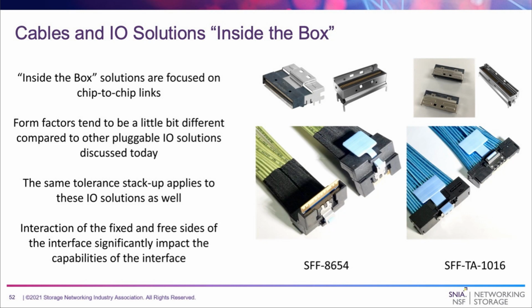These form factors are generally a little bit different than the box-to-box form factors we've discussed earlier in this talk, but they still tend to be available in 4 and 8 lane interfaces. And actually, these solutions have often already pushed density requirements to 16 lane and beyond, which is where pluggable I/O is trying to get to today.